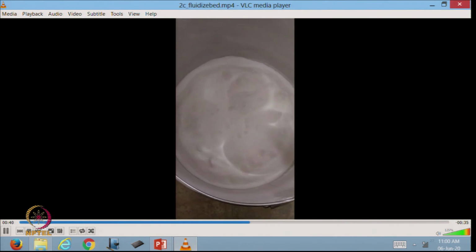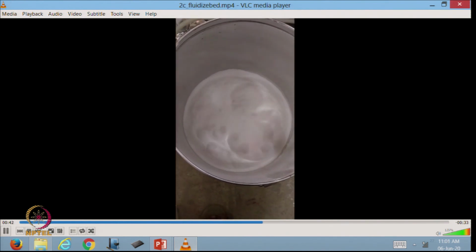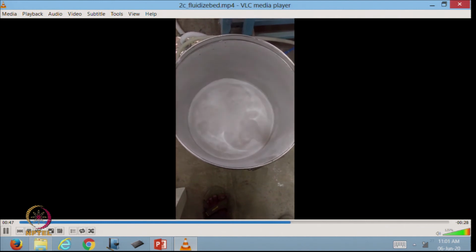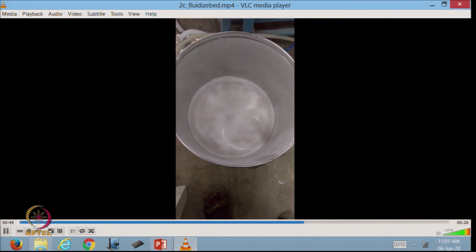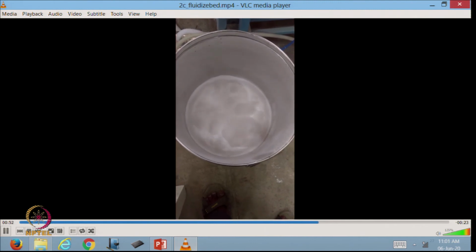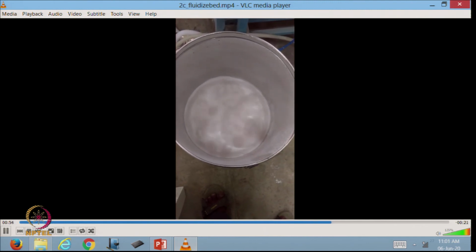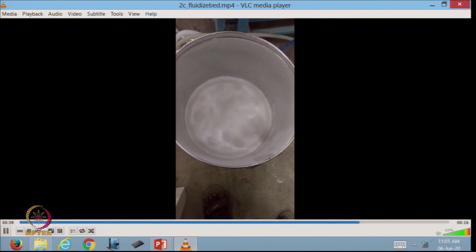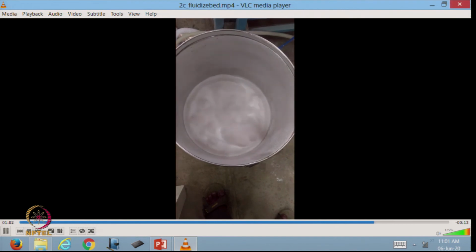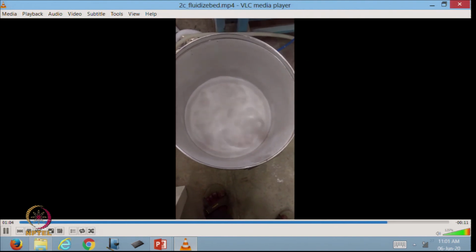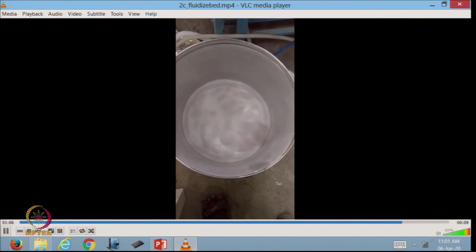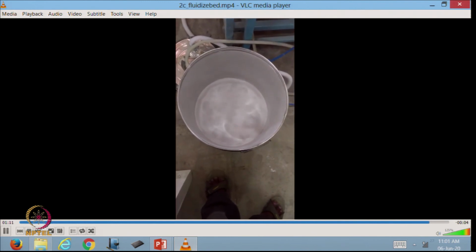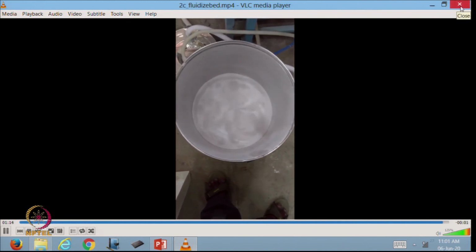This powder cloud is taken by the venturi pump, and then it is supplied to the spray gun. The powder cloud is formed, powder is coming out from the bed, and it is mixed with the air, just like boiling water, any boiling fluid. So, this is the fluidizing of the powder.